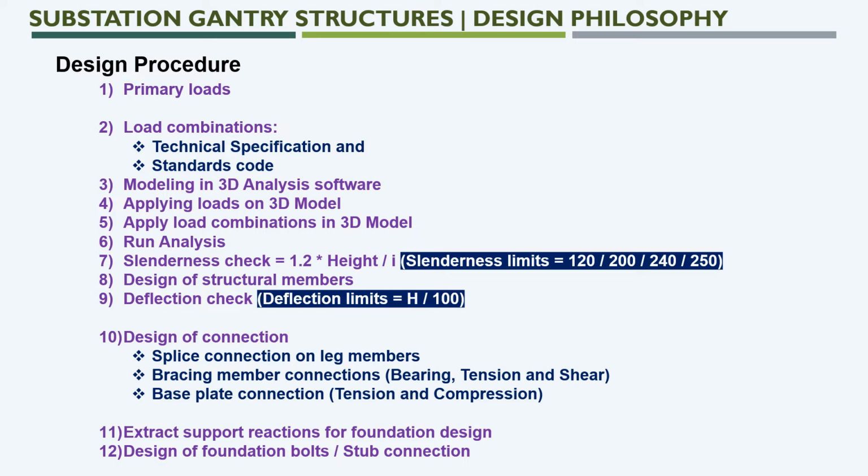And the next one is bracing member connections. So in this we need to check bearing, tension and shear. Base plate connections, we need to check tension and compression. Next step is extract support reactions for foundation design. So this is the input we need to provide for foundation design.